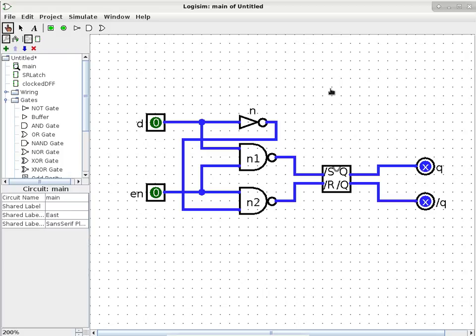Normally, when we talk about circuits, it is active high, which means when it's a 0, we don't mean to do anything, nothing to be done. When it's a 1, then we say, yes, go ahead and do something. In this case, it is the opposite. It is called active low. It's kind of like a P-channel transistor, where when the input is low, you turn on the device. It allows flow, but when the input is high, it is like, okay, don't do anything, break the circuit. So it's kind of the same thing.